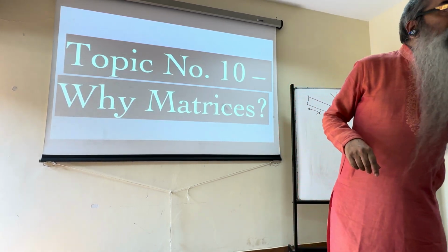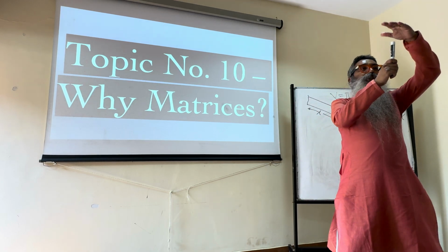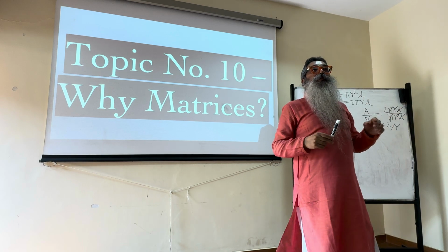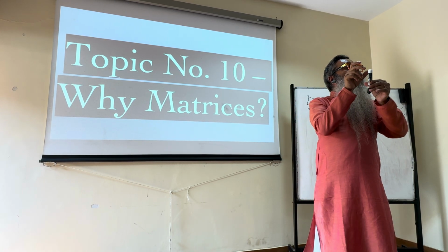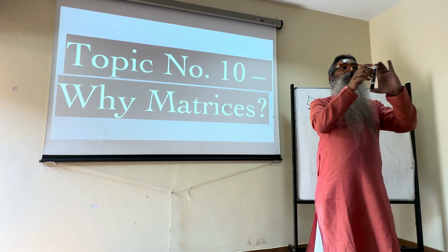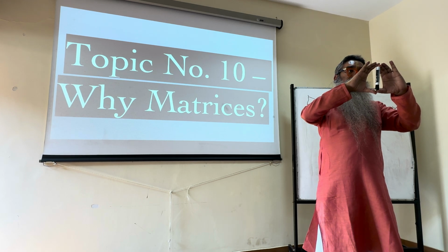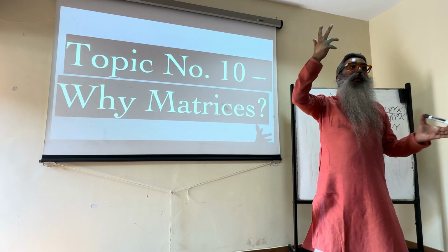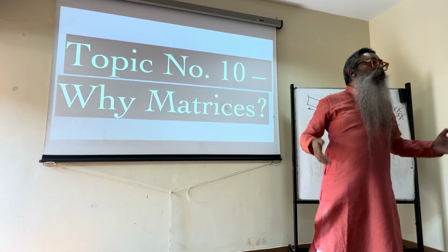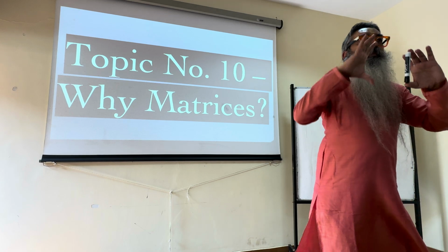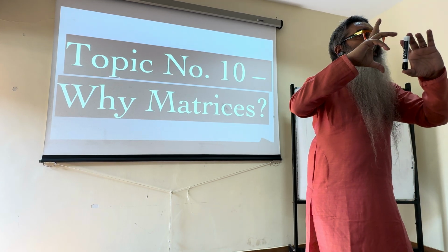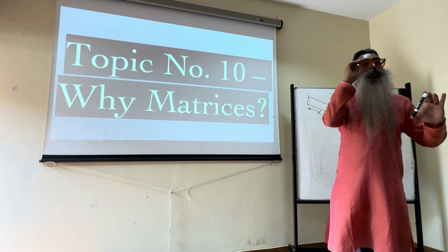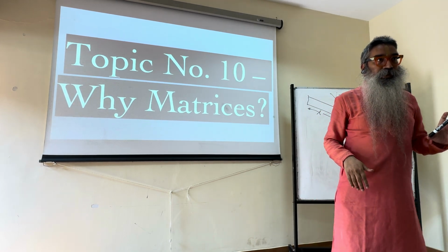Excellent, yeah. So we said that a rod is good in tension, good in compression. Once I keep decreasing the diameter beyond a certain value, your L becomes much larger compared to the diameter, then it becomes a fiber. Bending strength is very low and compressive strength is very low, right? If I take a strand of my hair and try to push it, I don't even need any force, it just goes off, right? So essentially it's a geometric failure, like buckling, but it's happening because of very, very low flexural stiffness, which is a part of the compressive strength that you're talking about, okay?